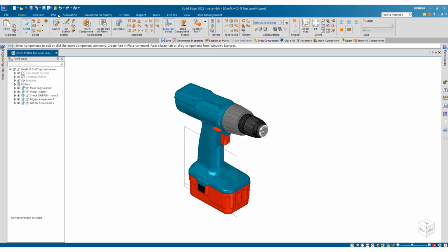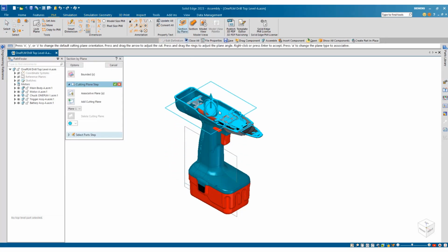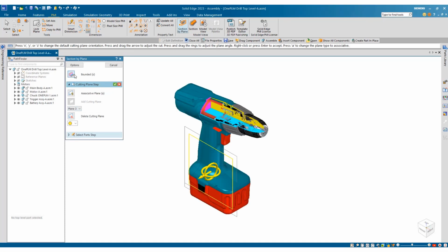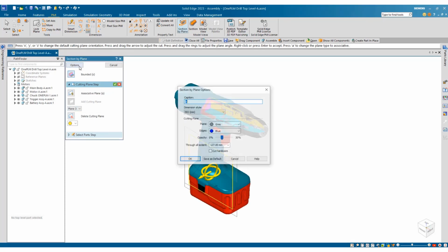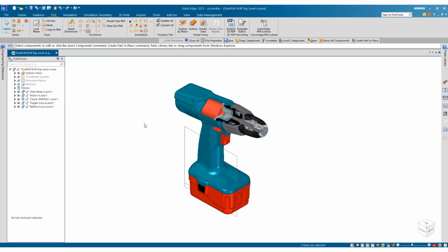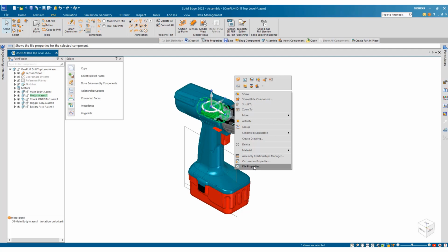We've also got the option for deciding whether we're going to cut hardware parts or not. So if we go and create a similar section to what we did before, let's just go and create these nice and quickly on here. But this time we've got a certain component, such as this cut hardware. So what we've done, the motor, we've actually defined this as hardware. So even though I have gone and selected on there, the motor has been defined as a hardware part. So let's go into that motor and have a look and see where we go and define that.